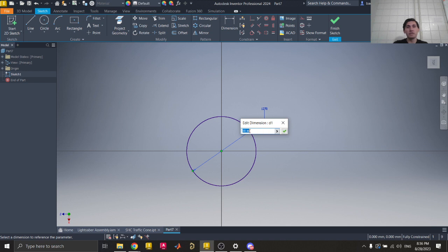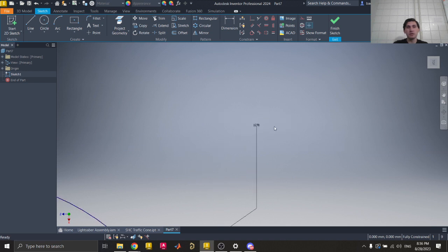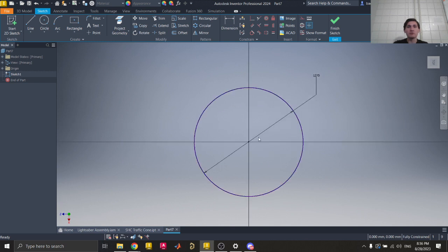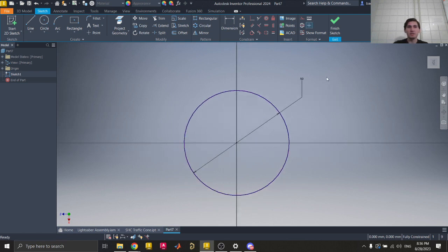but now I have something that is 50 inches in diameter, and it retains that number there, but then you can see here it's 1,270 millimeters. So I'm going to take that back. I'm just going to delete this inches part, and then hit enter. And then now it reverts back to the default units, which is millimeters. So now we're here.